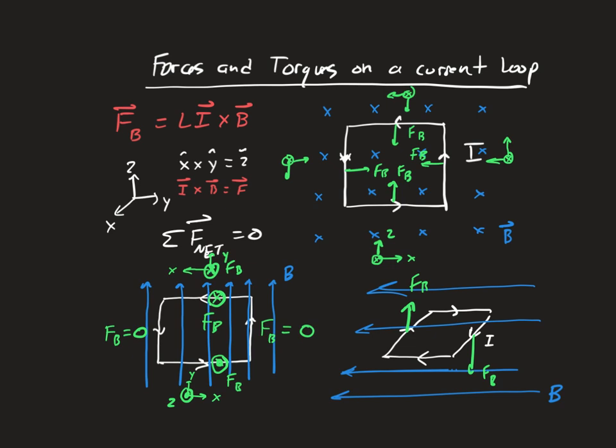So normally what we do is we fix a rotational axis here. You fix some kind of axle through the motor that way, and so the thing actually spins in this fashion. It spins that way. This is how you actually get electric motors: you have little current loops which are fixed to spin on axes, and the opposing forces are on two opposite sides of the axis.